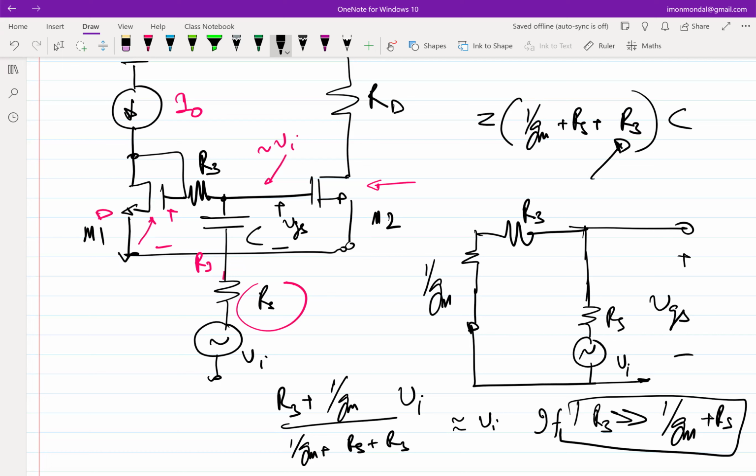Yes. With the addition of RC, okay, good question. So the capacitor will act as an open circuit for the question. So there won't be any current through RC. Let's assume there is a current through RC. The current through RC cannot go to the capacitor, it cannot go that side.